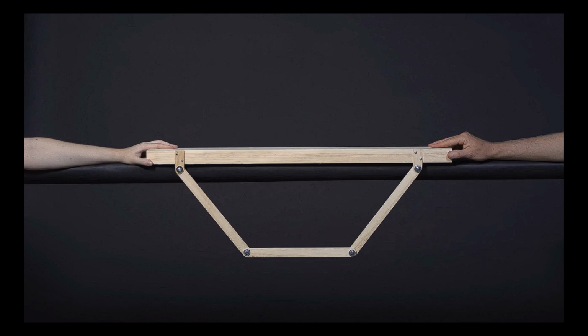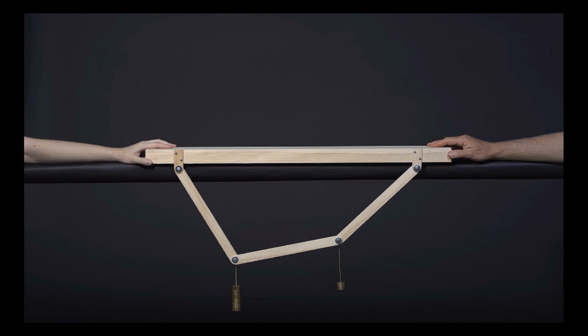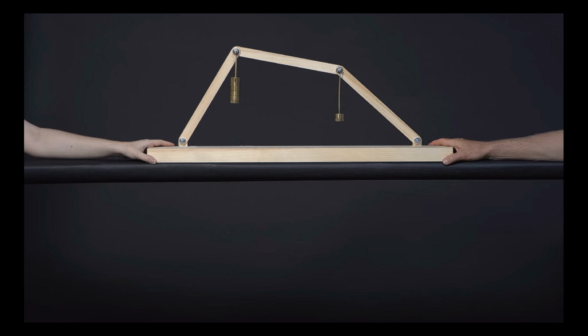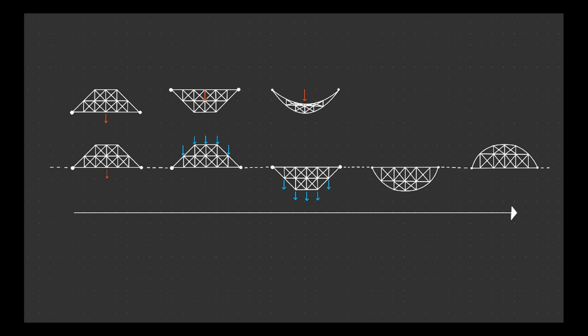So the question is, how can we figure out the shape for the arch? We just hang it upside down so that it works like a chain system. Then we apply the forces and turn it right side up. In our code, a very similar thing is used.